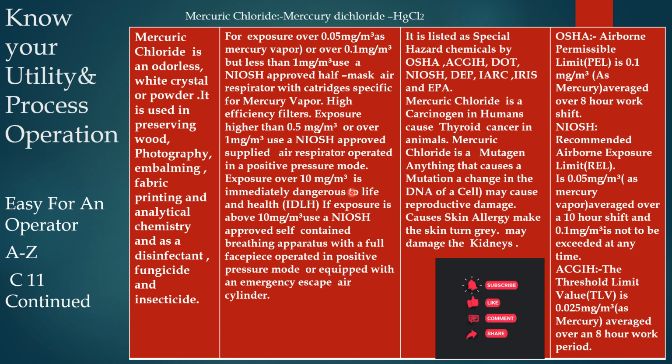Exposure over 10 milligram per meter cube is immediately dangerous to life and health. IDLH value: if exposure is above 10 milligram per meter cube, use a NIOSH approved self-contained breathing apparatus with a full facepiece operated in a positive pressure mode or equipped with an emergency escape air cylinder.